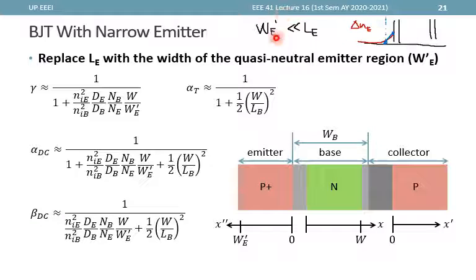Now, if there is no recombination, then why does this go down to 0? Since we normally have a metal contact, an ohmic contact to be specific, at the junction, any excess minority carrier concentration will instantly recombine. And so we are forcing this value here to be 0, and it will eventually follow this linear plot.